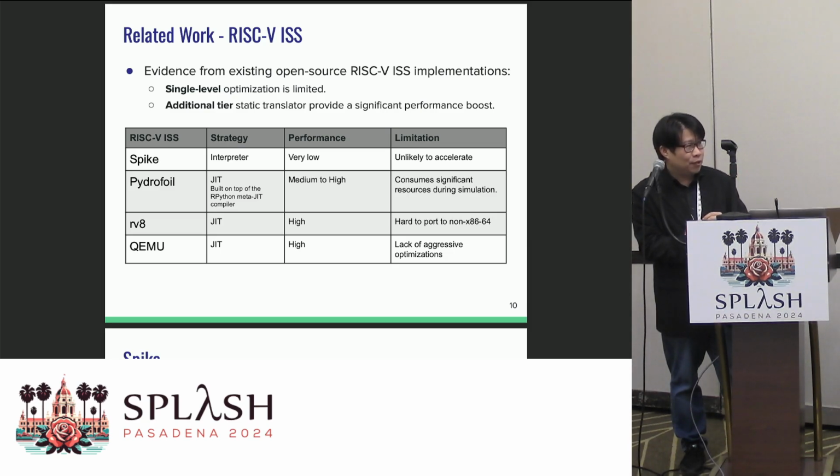And Pydrofoil is a very interesting implementation. It is built on top of Python, as part of the PyPy toolchain, and it can apply several interesting optimization strategies, making it possible to achieve a bit higher performance. However, it consumes too much memory, making it almost unsuitable for multi-core system simulations.